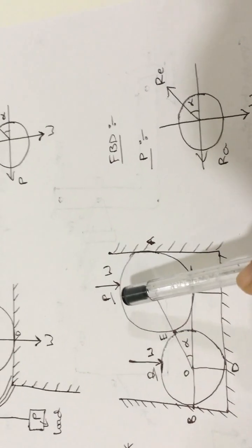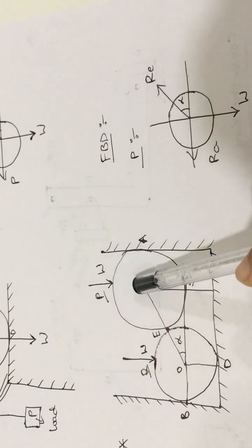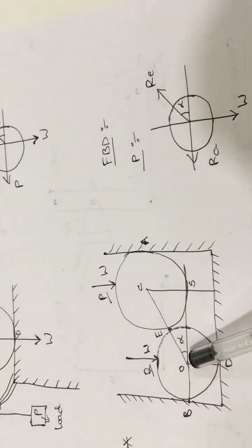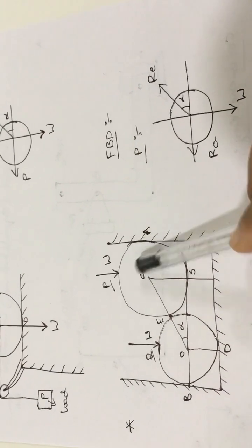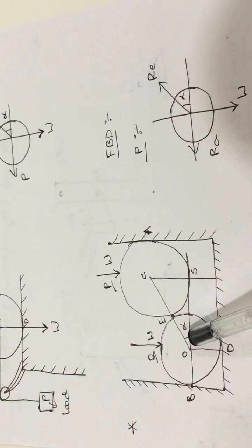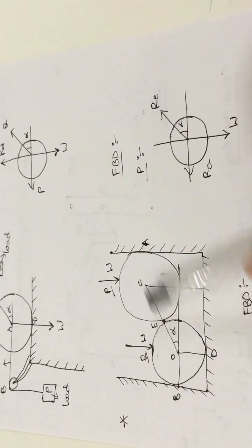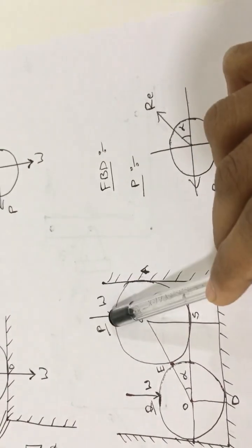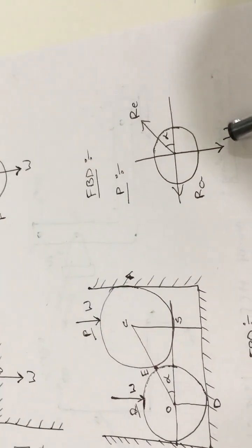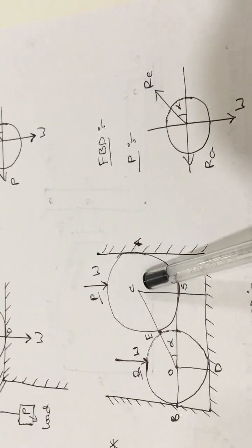And next, when you are drawing the free body diagram for the P ball individually, the Q ball will act as one of the supports for the P ball. So this Q ball is the second support. Only two supports are there. So by eliminating these two supports, you will get two reaction forces. Now here weight will always act in the downward direction, so that is the direct force W. So completely three forces you will get in the free body diagram for the P ball.